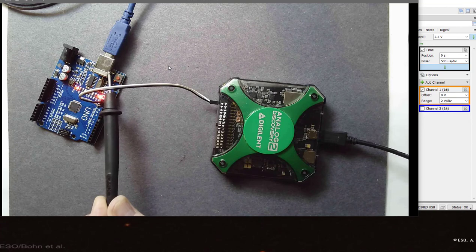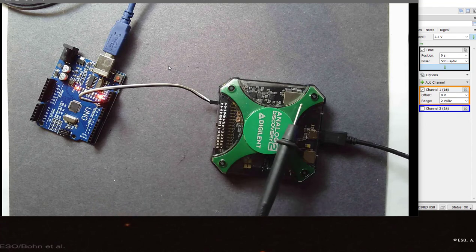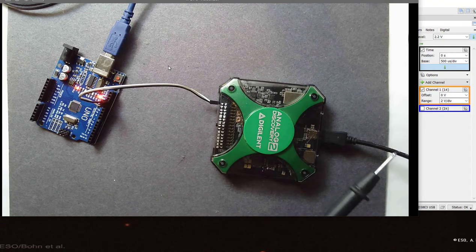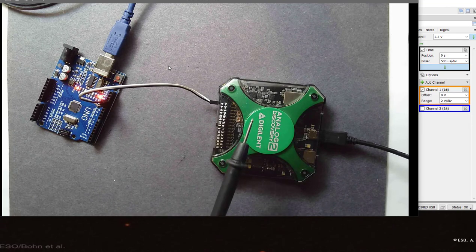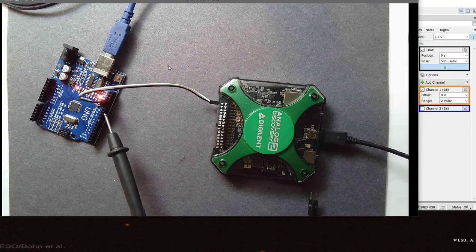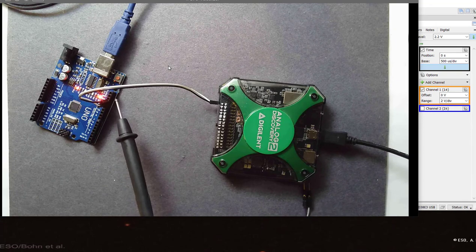So the ground is connected to the USB hub, and likewise the ground on the USB connector here is connected to the USB hub, and so those grounds are at the same voltage, and that means that I don't have that common signal noise that's introduced in the artifact. Always be careful to avoid that problem. So I'm really measuring the single-ended voltage between pin 13 and ground.